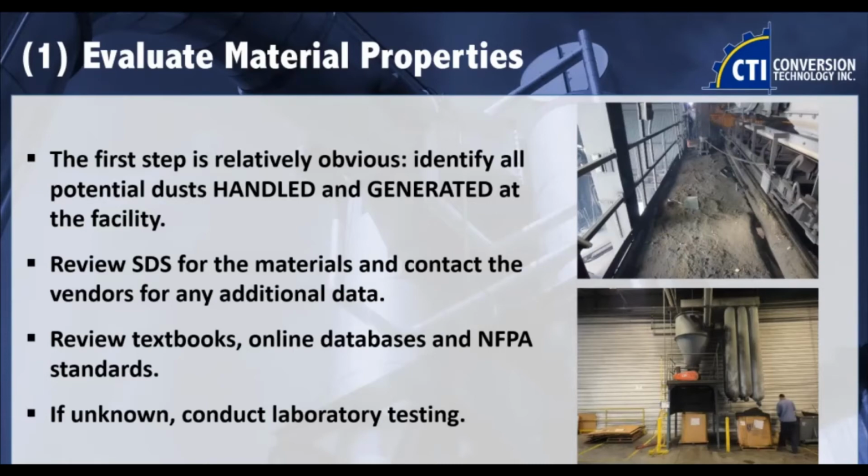So it's your SDS. So if you just don't know, and there's no real way for you to determine it by reading, you can conduct laboratory testing. I will say for laboratory testing, for those of you that might have reached out to other people to do DHAs, I just find this a lot. I would not say you have to do laboratory testing on every single powder at your facility. Some people might disagree with me, but it is very expensive. If you have 50 powders that you deal with, that's 50 explosibility tests at $1,500 a piece.